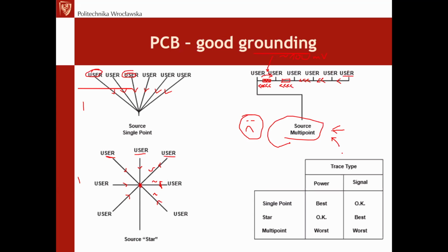But this hundreds of millivolts voltage drop generally adds a direct noise to our design. So if you are designing anything requiring low noise operation, this technique is definitely out of the question. So be very careful here. Try to avoid this technique as much as possible. Use one of those. Those techniques are both good: single source point and star point.